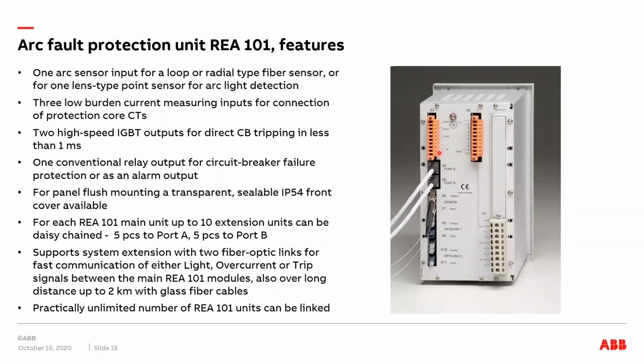One conventional trip output, we have also electromechanical relay contact to provide, for example, circuit breaker failure protection, or it can be used as an alarm output. Then for panel flush mounting, we have an accessory sealable front cover, just a transparent polycarbonate cover.